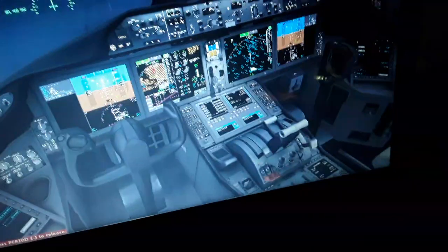So we have the FADEC to control the functions of the engine. The FADECs are the full authority digital electronic control computers, one installed per engine gearbox, dual channel redundancy, one channel fails, the other takes over, controls monitors, it displays all the engine data. I just showed you in the display in the multifunction display all the EICAS, engine indication crew alert system display. Also this can control monitor fuel flow, fuel metering unit, fuel heat exchange sensors.